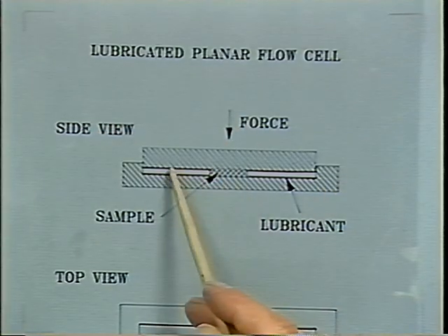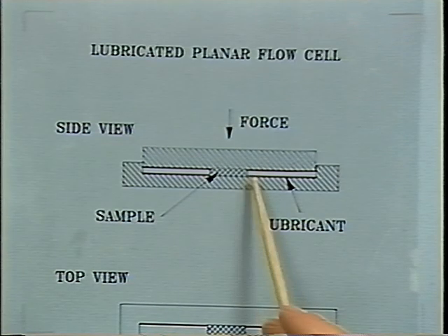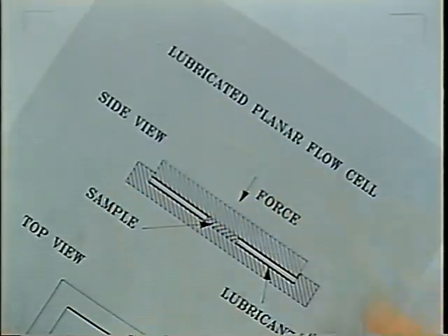So we have a mold which has lubricated surfaces on the side and top and bottom, and there we're squishing this sample and making it long. In that squishing, the stretching of the sample produces an ordering of the domain structure, and we will study this ordering using TEM and also using small angle X-ray.